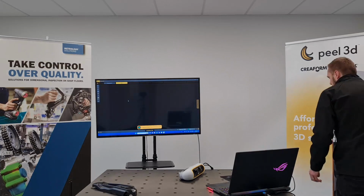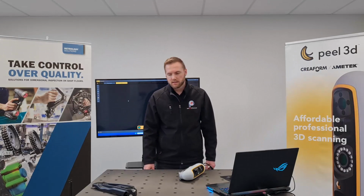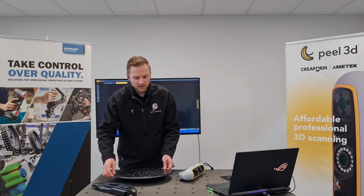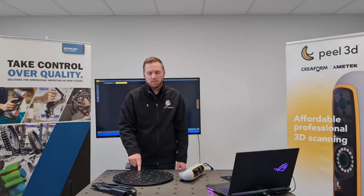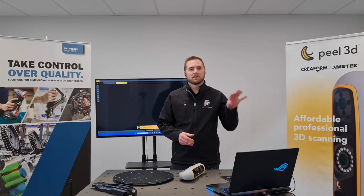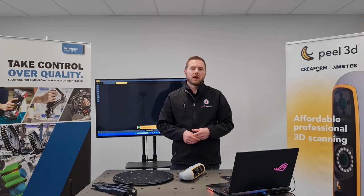And I always put the calibration plate right back into the box to ensure that it's kept nice and safe. So next, I'm just going to use this little turntable. It's just a very manual turntable with a few targets on it. Great for small parts. If you've got a part that you're scanning, or a car, for example, just put the targets on the car, and it will ensure that if the car moves, the scanner's going to track any movement.